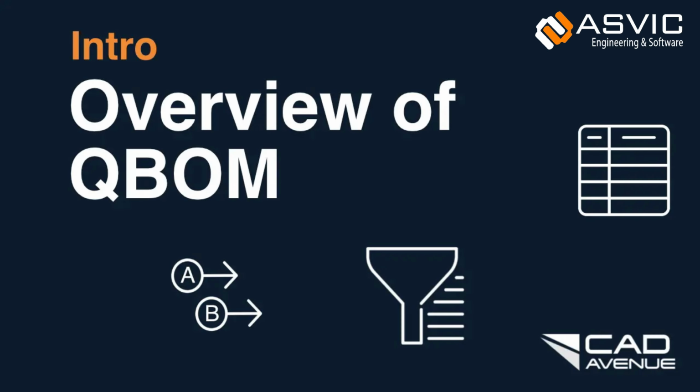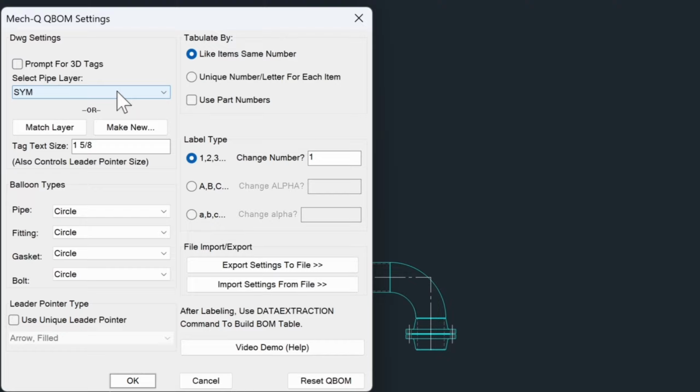QBOM settings if this is the first time you've loaded it in the drawing. Now, QBOM only has one dialog that you'll have to worry about. It includes a toggle for 3D. You'll have the option to select a pipe layer to put your bubbles on. You can match layer or make a new layer. Then you can specify the actual text size inside your bubble.